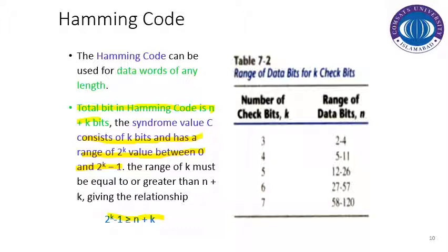Well, students, this was all for today's session. We have got the introduction to the Hamming code that is used for the error detection process, and that is utilized in a RAM in order to identify the error, so that we can correct it and revive our data, and eliminate any errors that are occurring in the data. And we've seen that the Hamming code is constructed in such a way that we add some redundant bits at some specific placements.